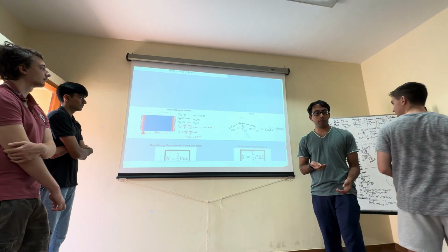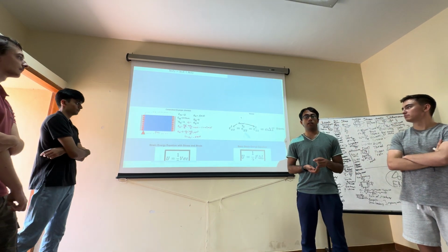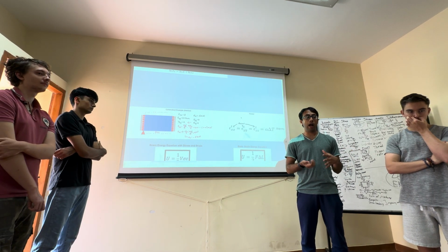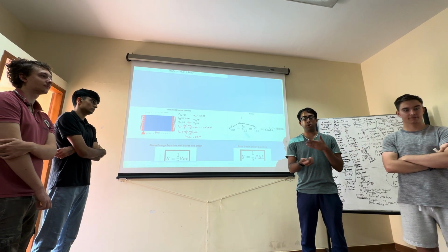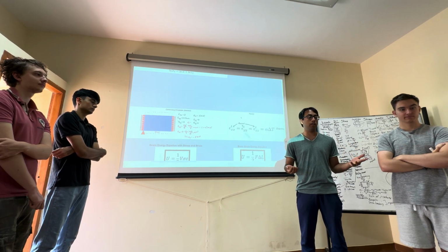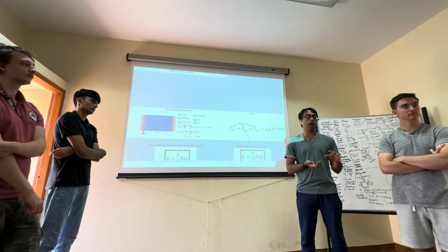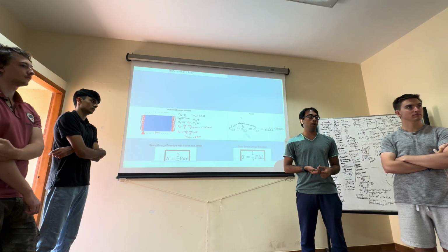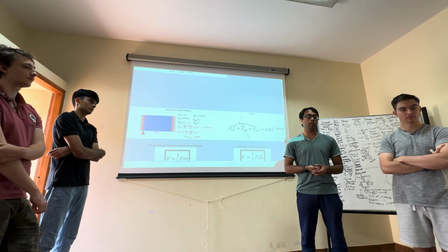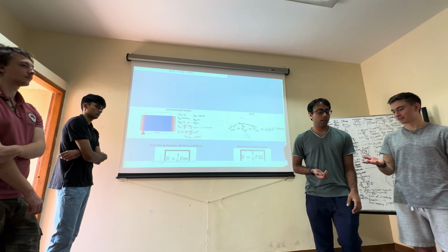So when we talk about loading conditions, another load that occurs is temperature change, because materials have thermal expansion coefficients that determine how much they will expand under a temperature change. This can become an issue in engineering or in structures in general if you have a temperature change, or a difference in the coefficients, where you can cause two metals to either contract or be in tension based on the relation between their coefficients.